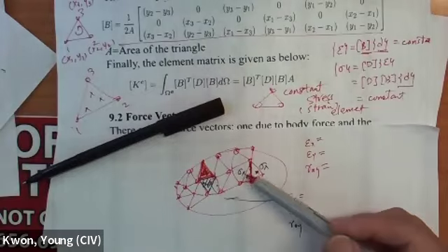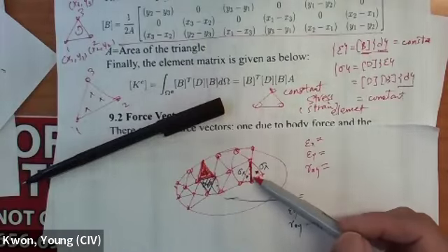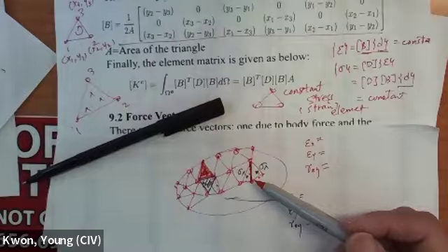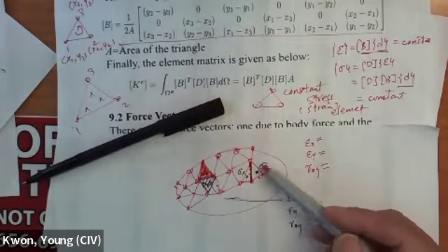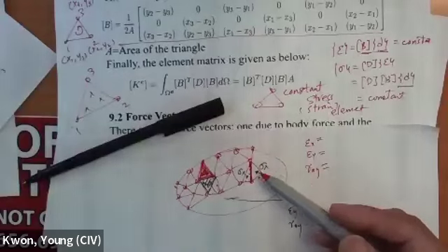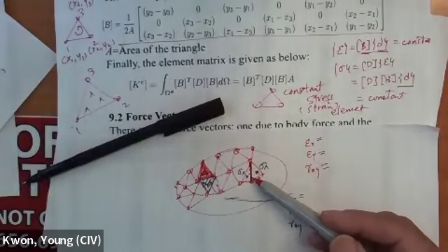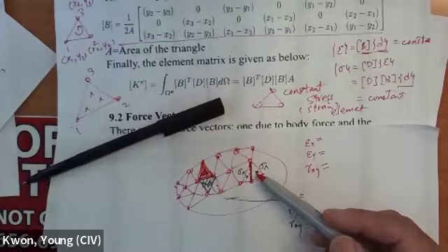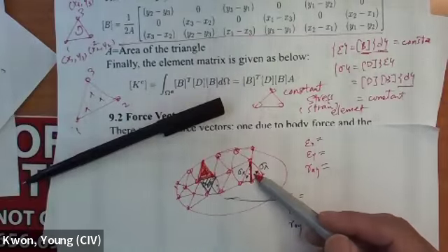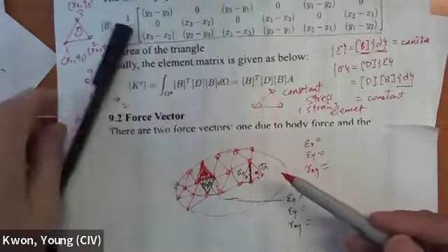So at least at the interface, they do not satisfy that stress equilibrium. Make sense? But the deformation is going to be continuous, because we cannot have a jump of the deformation all of a sudden, which is not physically acceptable. So deformation is continuous, but stress and strain may be discontinuous, some kind of jump from element to element, because of that approximation.